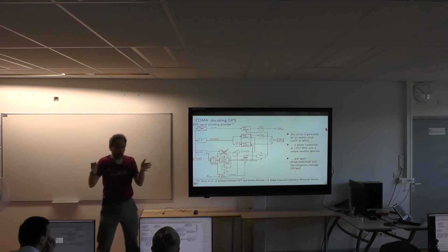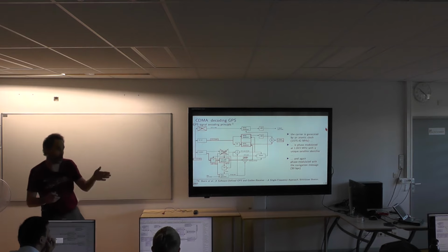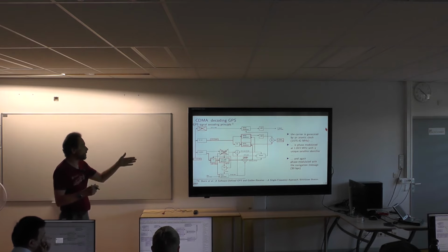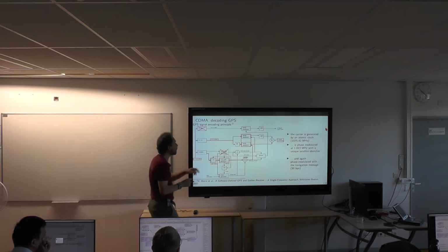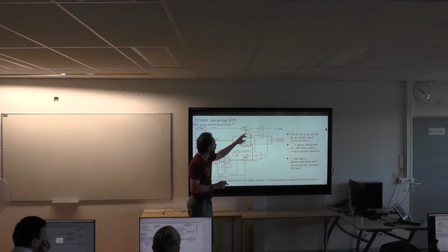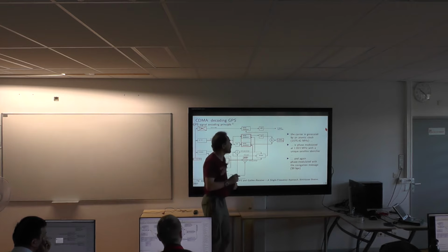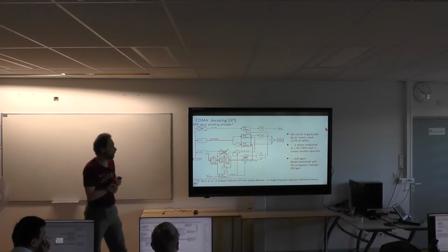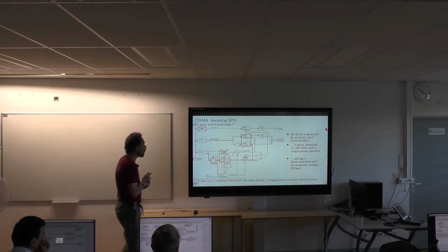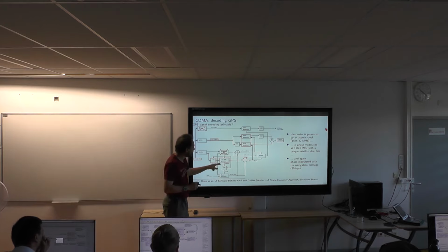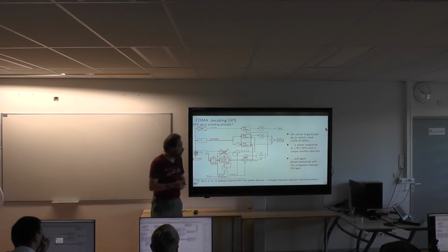We're going to see together what BPSK modulation is. You encode on the phase, 0 phase for bit 0, pi phase for bit 1, and this is your BPSK modulator that generates the output on the L1 band, the CA code. Finally, the code is a unique identifier for each satellite, but there is a payload.